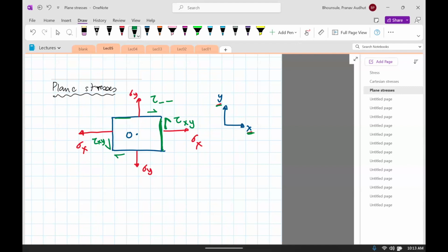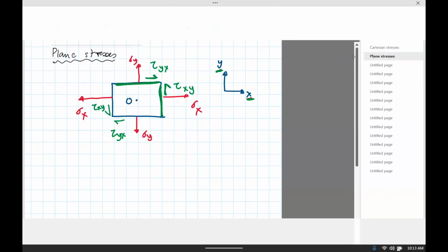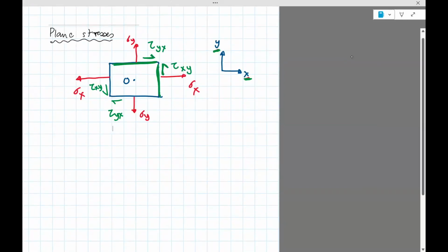You can see that the plane is the top plane. The top plane has a normal in the y direction, so y. And then the direction of this stress is in the x direction, so x. So you can reason out the same thing. This is something you have probably seen many times, was this in strength of materials?